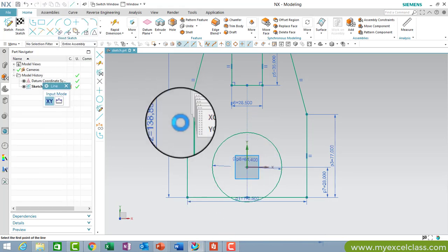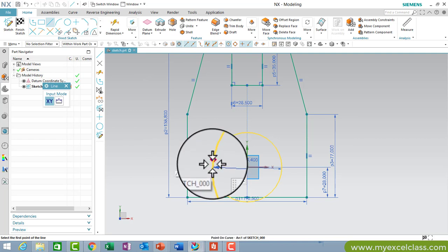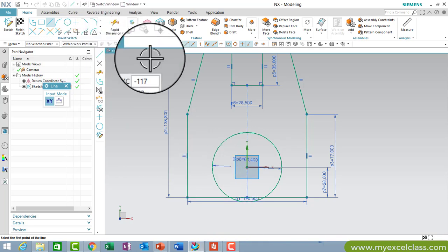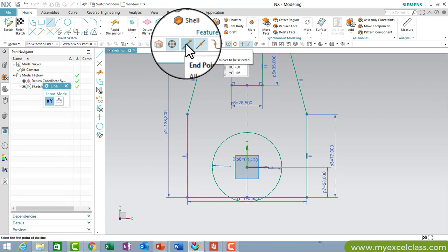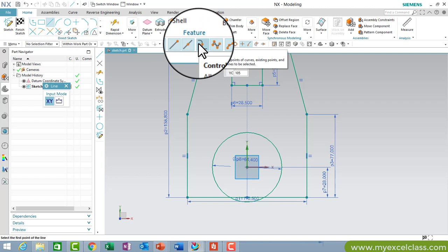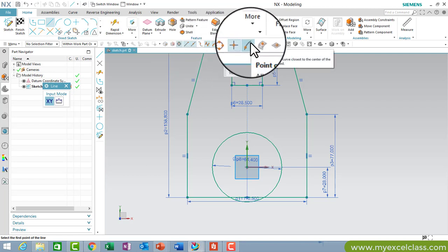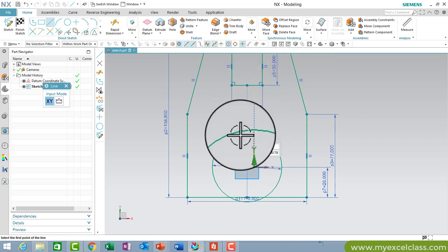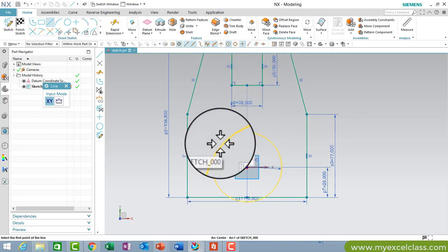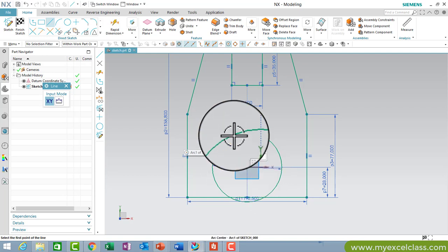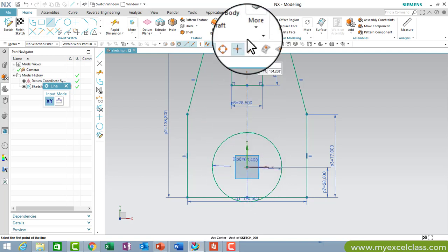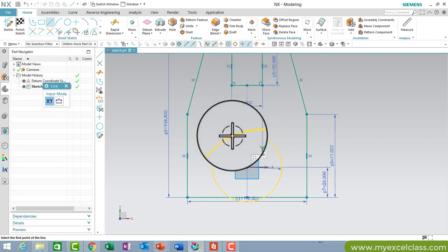So I'm just going to select line, just click anywhere on the surface, and if you're not able to pick, if you see this particular thing highlighted in blue and red, so if you see here on the top, you have all these selection filters. Okay, so it has the end point, midpoint, control point, and there is something called point on curve. If this point on curve is switched off, you will not be able to select anything. If you see the red and blue is just highlighted here, it does not highlight it here. Okay, in case you have that problem, just make sure the point on curve is checked on. Okay, so you'll be able to drag it.